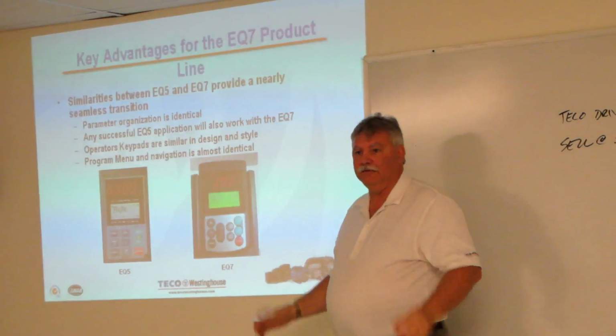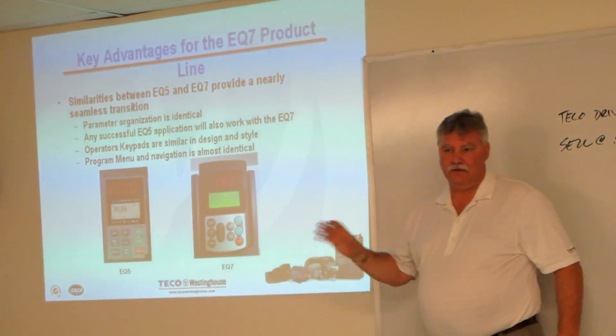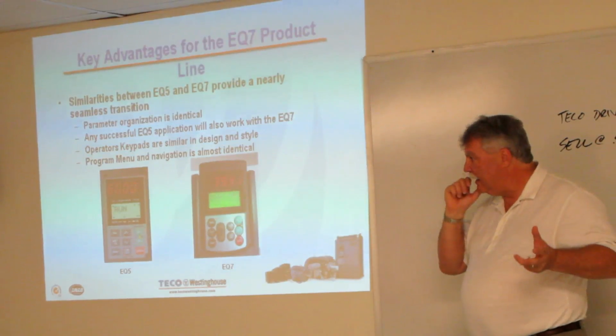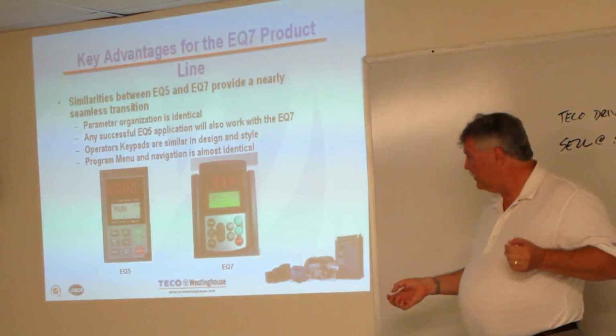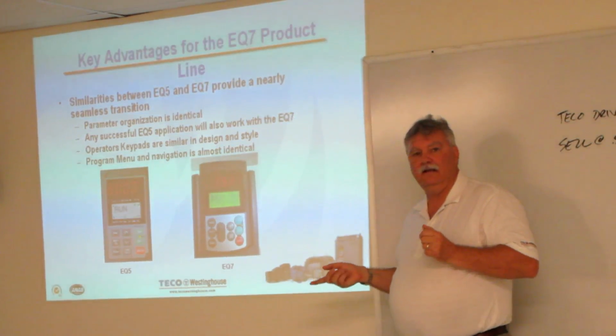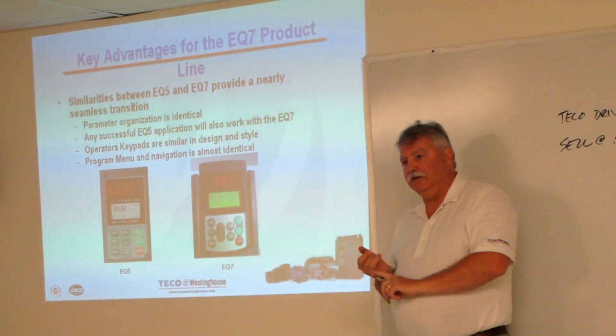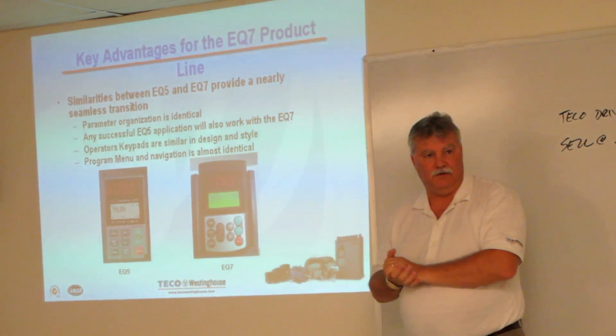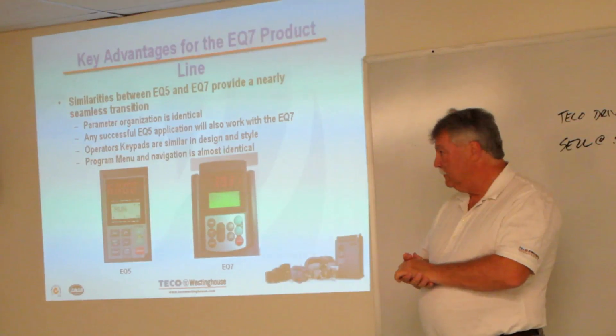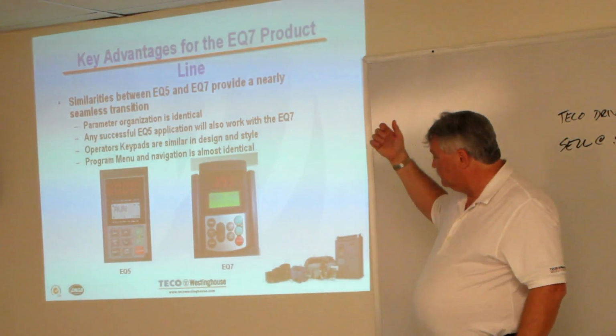And that's great for starting something up and making sure the motor's running right. If you happen to have a PID loop on this, you're trying to control tool pressure, there's another screen you can bring up that looks at your set point, the feedback, and the process output. So you can do your comparisons and analyze what the PID loop is doing.